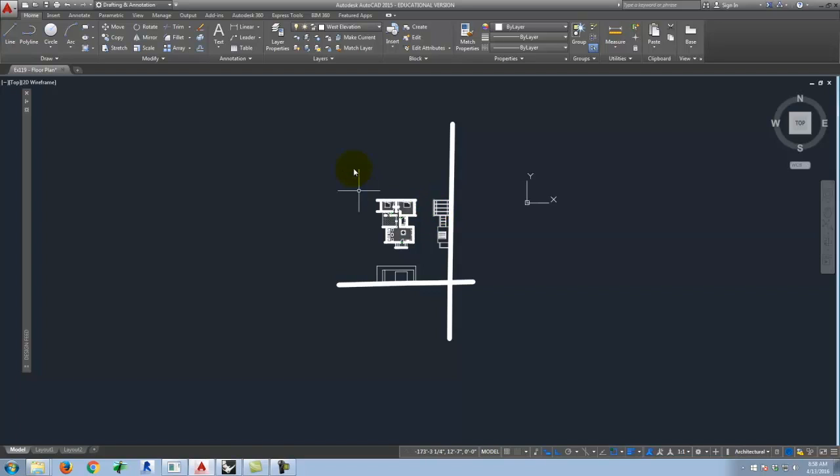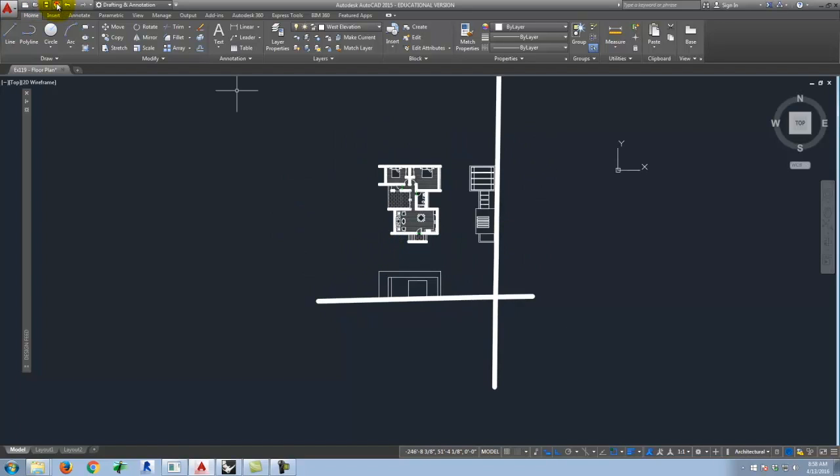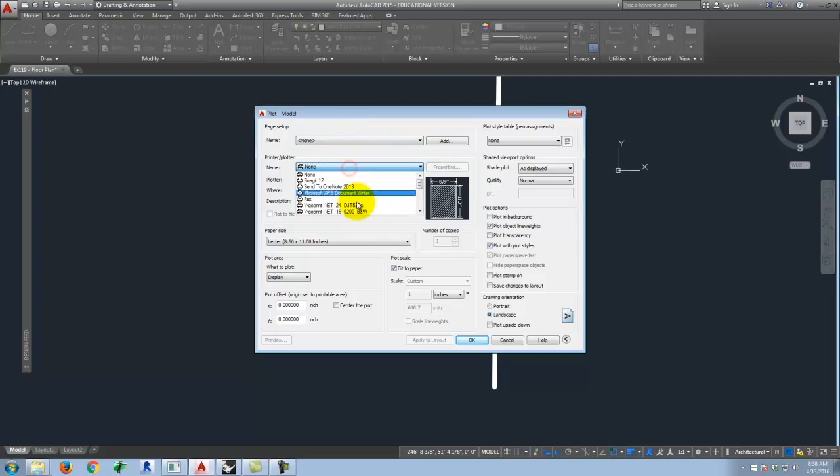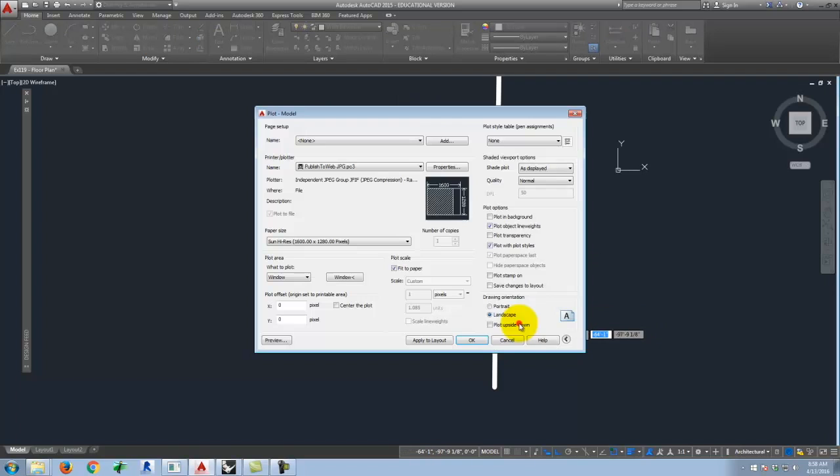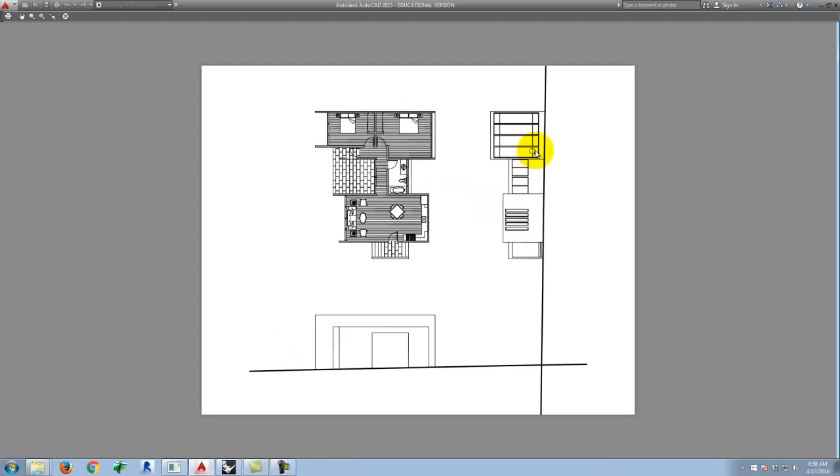No? So the goal today is to get your elevations out. When you're done, you're going to do the same strategy of printing to a JPEG. So we'll go down to the print to web JPEG, use the custom paper size, and we'll put a window around the whole thing. And you'll end up with something like this that has your building, but then has your, hopefully, 4 elevations. We're shooting for 4 elevations when we get to the final, or not the final, sorry, the assignment 105. So we'll ultimately be working there, but you're going to get as far as you can today with elevations. It may only be 1. All right?